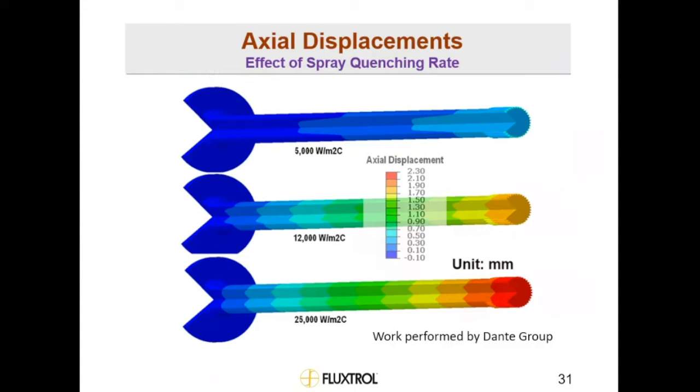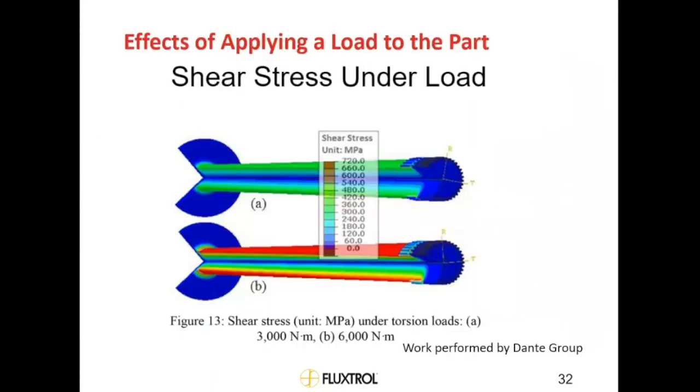So what we saw was that these things were really moving a lot during the process. It explains why a top center that constrained the axle was causing bowing or bananaing of the axle shaft, which is why those constraining rollers really helped to keep things aligned in the induction coil and the part straighter.